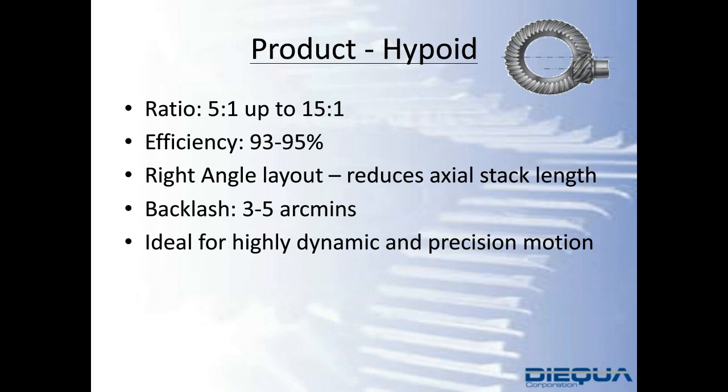Okay, so let's start off with a hypoid unit. A hypoid unit, you might take a quick look at it and see, well, that's the Bevel Gearbox, so that's a spiral bevel gear, right? You might not be too far off, actually. It's in the name, it inherently says the hypoid hybrid, if you would. It's transitional between a bevel gear, where you would have the center line or center axis of the input gear and the output gear on the same plane, right?